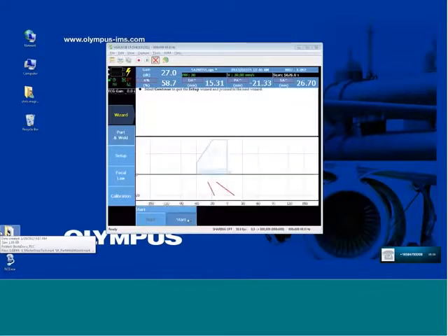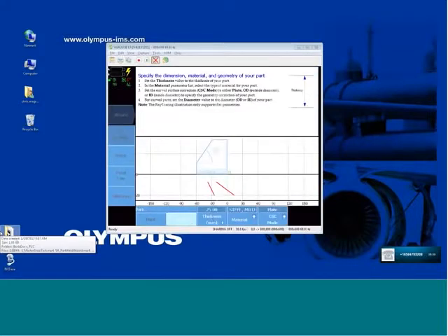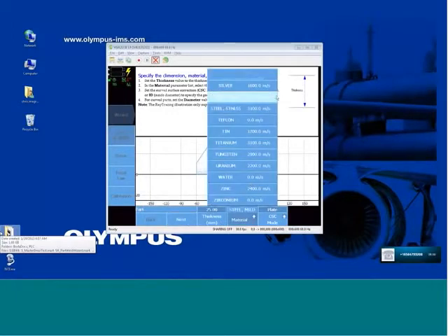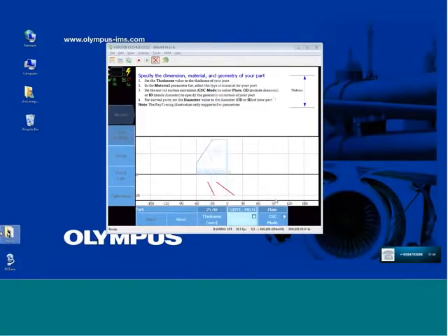function. Selection of start, enter the material thickness. Again, it has nothing to do with the component's beam formation. It's just the skip lines. We will select velocity from the database. And we will select plate for piping girth welds or for plate geometry, meaning that the ID and OD surface are parallel and not curved.